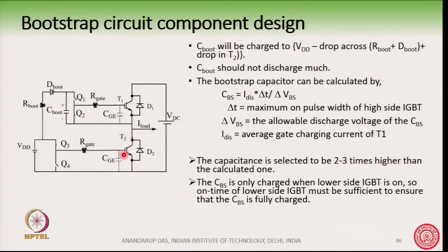You should also note that the lower side IGBT should be turned on for a sufficient amount of time, so that this will be fully charged up.